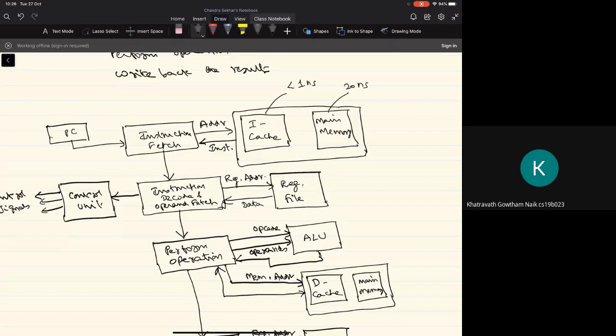And like we have seen, what is involved in accessing the contents of the register file? Basically, I perform the read operation. That involves using the read port. And earlier we've seen that the read port is nothing but a demultiplexer. So it's the delay of the demultiplexer. There's nothing more than that.